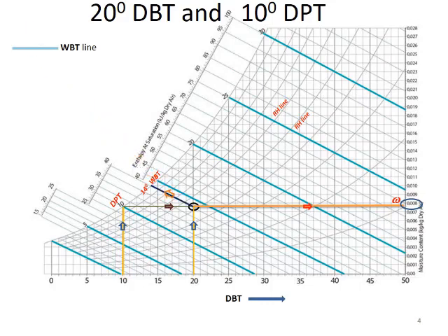And then if you want WBT, so from that point you have to move along the constant WBT line till it intersects saturation line. So there you may not be able to read what exactly the number, because numbering is not there. So in that case you come down. So if you come down, it reads as 14 degree WBT. So reading from DBT scale itself. But how you got that point, that is very important. So from that point, you have to move along the WBT line till it intersects the saturation line, then you have to come down.